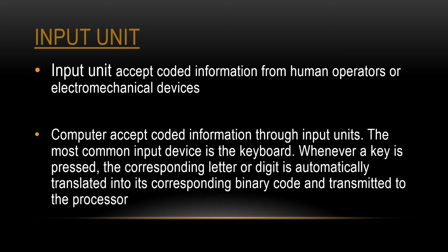Then microphones can be used to capture audio input, which is then sampled and converted into digital codes for storage and processing. So you can give input through the microphone. The microphone can be connected with the help of a connector, and directly you can give the input to the computer. Now this will be converted to digital codes with the help of an analog to digital converter, and then it will be stored and processed.